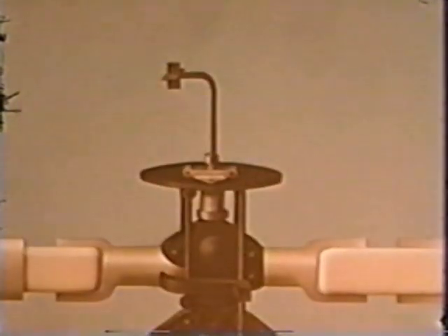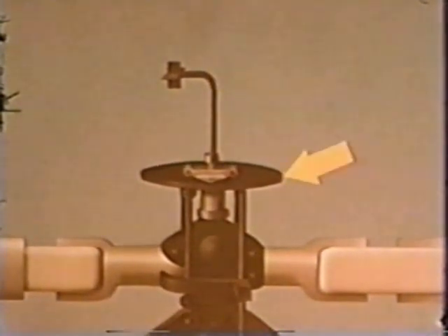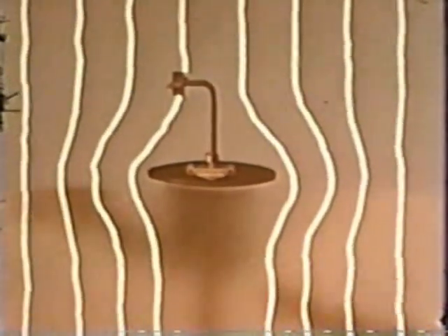Now let's look at the drone's translational flight characteristics. At the top of the rotor shaft, there is a static pressure pickup tube. It senses atmospheric pressure for altitude control during flight. A deflector plate prevents excessive airflow past the orifices in the pickup tube. Air flows downward past the pickup when the drone is hovering.